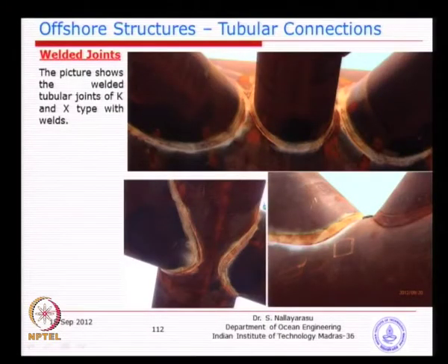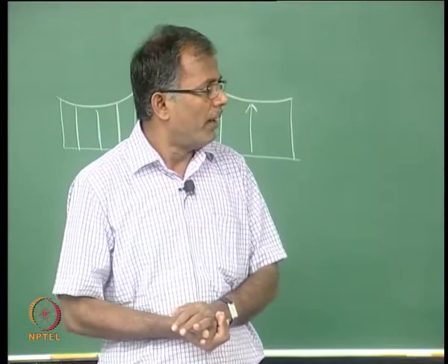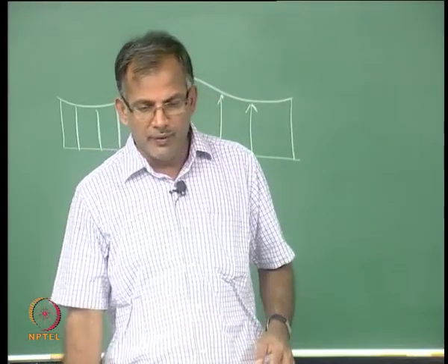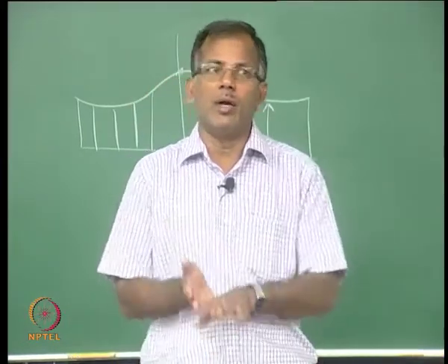This typical joint, you can see a fabricated joint, of course a little bit blur here because of this, but otherwise clearly indicating multi-pass welding and gap available. So, you can see here in this particular location, though we have given 3 inches in this particular project, you end up actually having very small after the welding, because the weld has taken most part of the space available, and that is one of the areas where you do not want to have weld overlap or weld on weld.